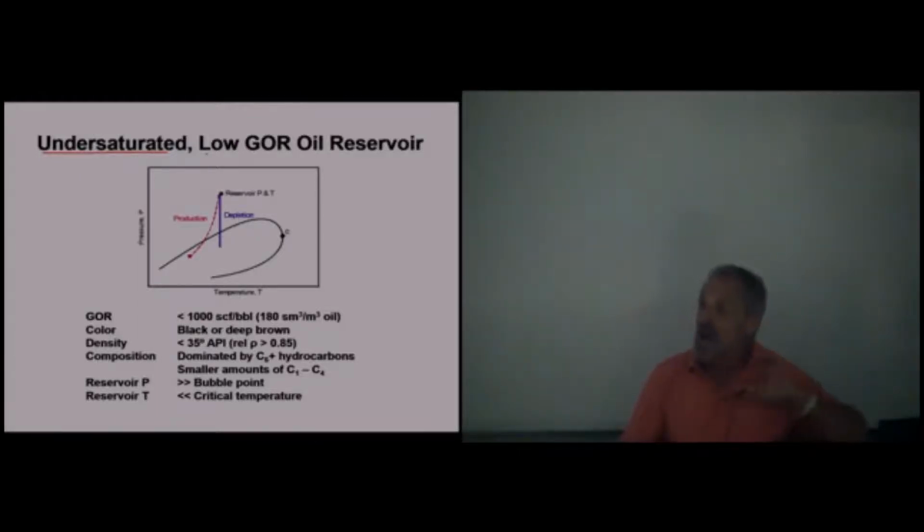So I can add more gas to the system and keep it a liquid at that pressure and temperature. So it's undersaturated. I always like to think about the salinity situation. There's a certain amount of salt I can put in the water before it becomes saturated, okay? So it's undersaturated. Now, if I started adding gas to this system, what would happen is my phase envelope would